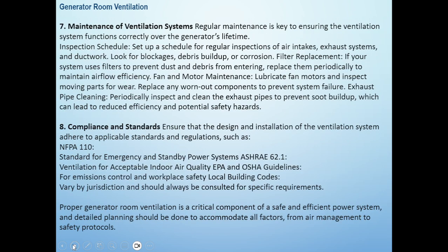The maintenance of ventilation system. Regular maintenance is key to ensure the ventilation system functions correctly over the generator lifetime. Inspection schedule. Set up a schedule for regular inspection of air intakes, exhaust systems and ductworks. Look for blockages, debris buildup or corrosion.